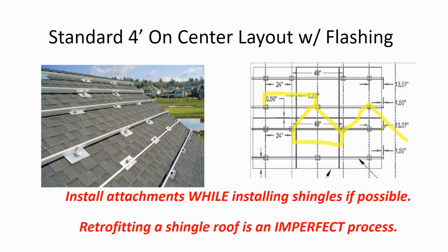Now, not all rafters are 24 inches on center. A 16-inch on center rafter is common as well. And so during the site evaluation, what I do is I get in there and I measure the rafter spacing, and then in AutoCAD, I locate every single attachment position.